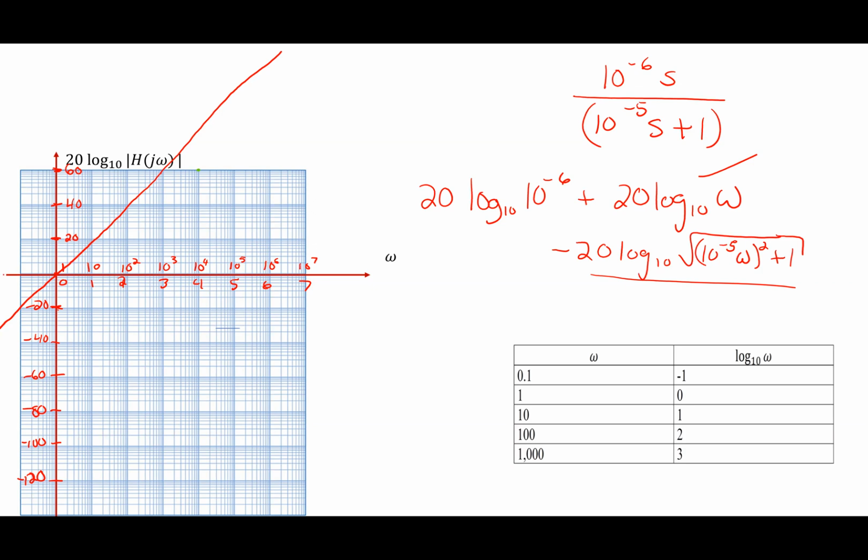In this case, I draw him out like this, out to 10 to the 5th. And then he falls at what slope? Negative 20 dB every decade. It's going to fall like that. The next job for me here is step 4, which is to add those two things together. And then I'm going to deal with this guy by himself.